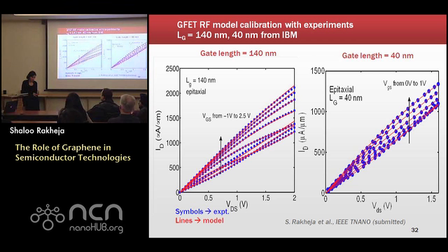So in this, overall we had 7, but having said that, I did a lot of sensitivity analysis to remove certain parameters, like I'm not optimizing beta, for instance. I'm going to take the electron and hole branch resistances from measurements and things like that. So we did it one by one. We started with just 2 basic parameters, mobility and VXO. And then we started optimizing more and more and started to see where we get that best point. So 7 is, I think, total.